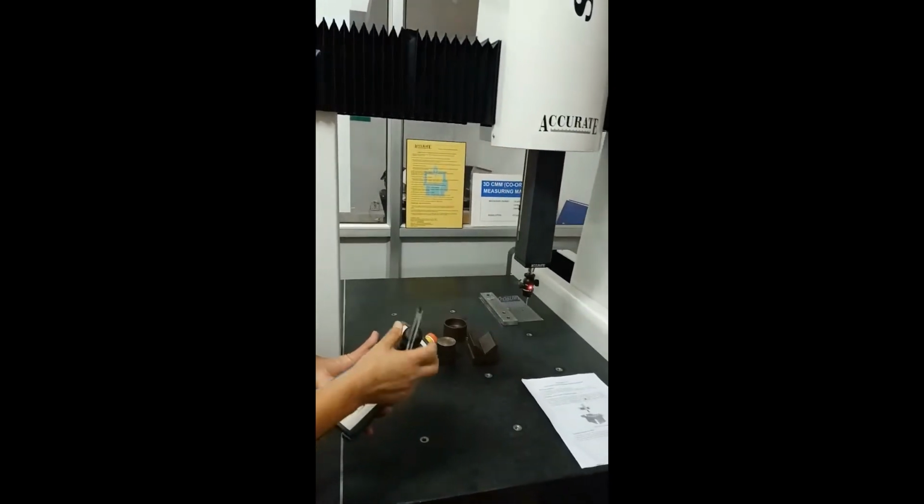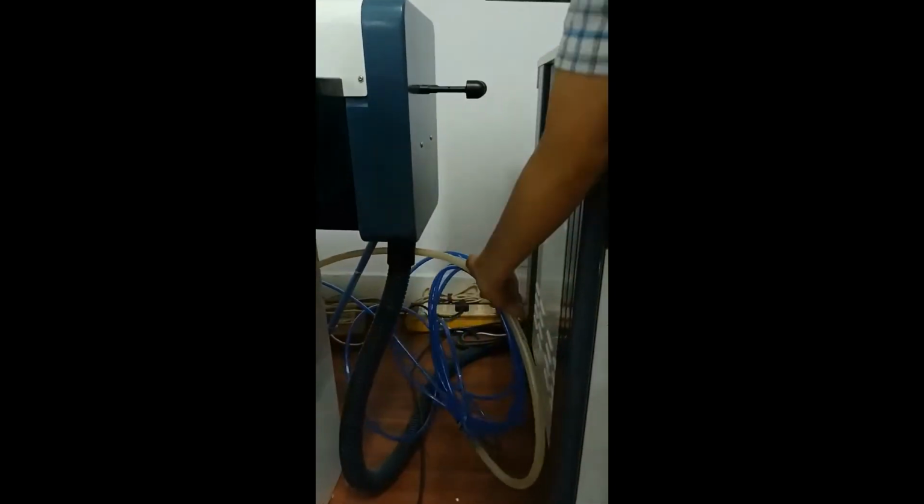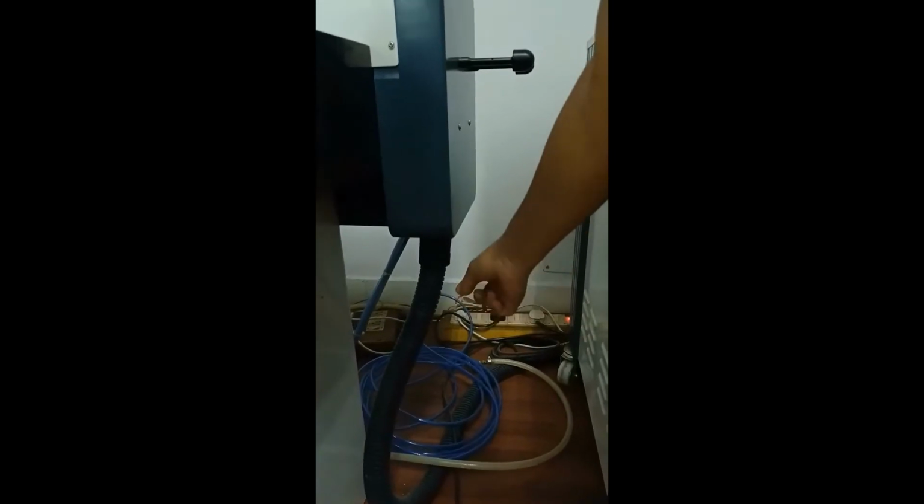Now, dear students, let us see the drive system here. How the drive system is working. So this is the joystick. There are four servo motors driving here, but for lubrication purpose we are using air bearings. For the air bearings we are supplying high air pressure. The air pressure compressor is running outside, and we have a hose pipe here. Through the hose pipe we are supplying the air inside the machine. So you can see the air bearing here.